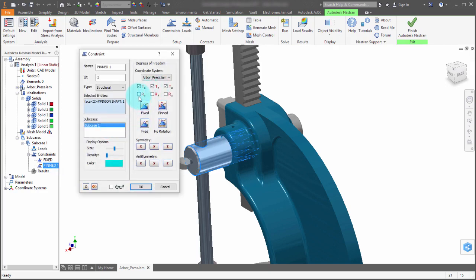And what I'm seeing here is that I'm allowing it to rotate in all directions. Well, you know what? Realistically, this is not going to be able to rotate. Remember, I'm using the global assembly. This is not going to be able to rotate about the Z axis. So I'm actually going to prevent it in that direction. So just because you pick from a preset doesn't mean that you can't go in there and alter it after. So you basically pick the preset that's the closest, and then you go in there and you alter how you want that to be assigned.